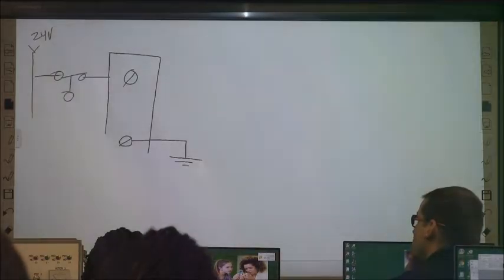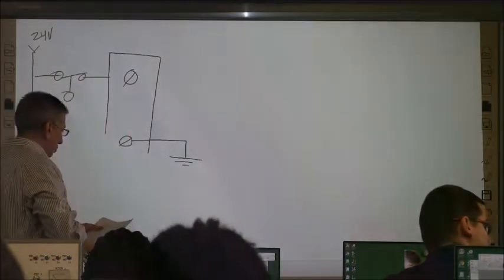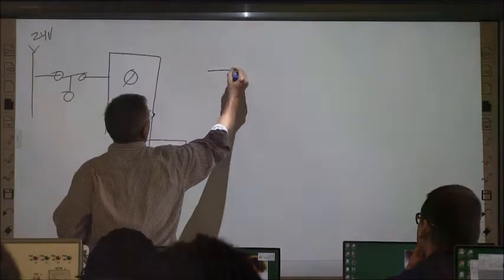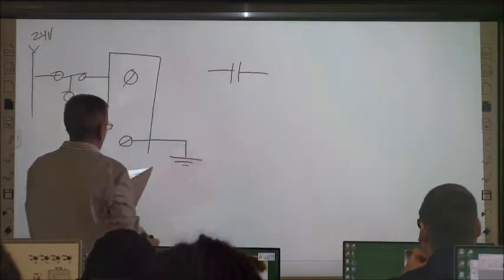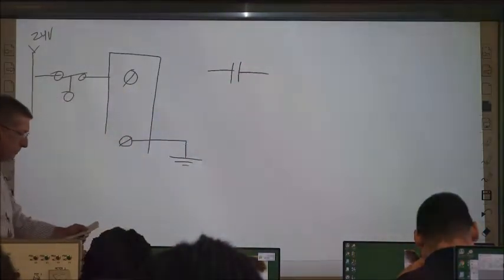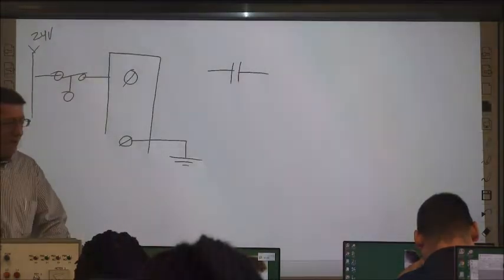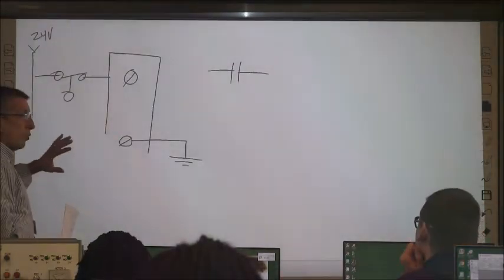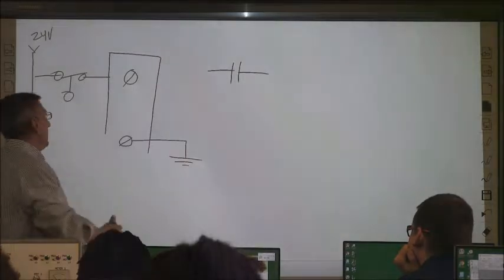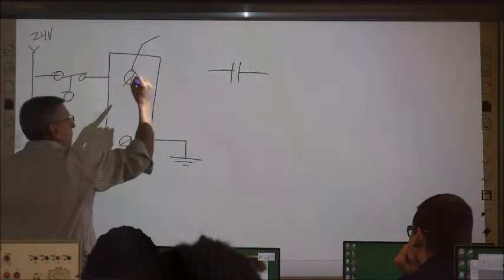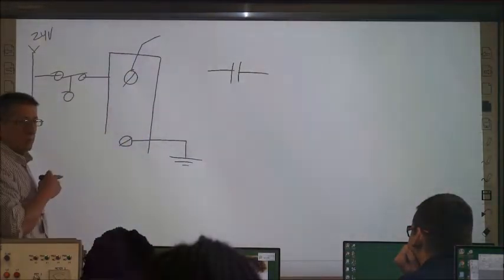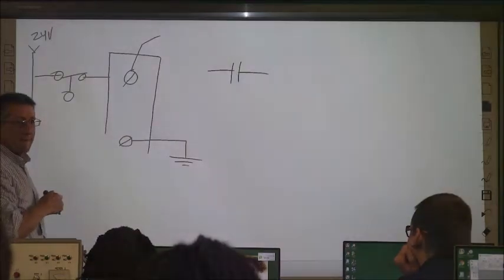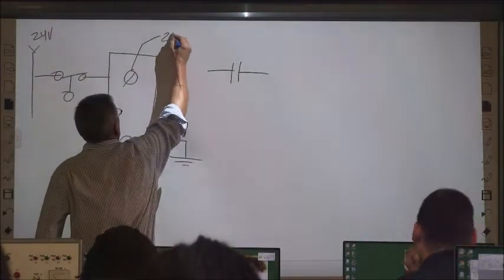The logic for the float switch uses an XIC instruction, but the instruction does not have logical continuity. So right now, while it's in its normal state, what voltage are we going to measure on this input? 24 volts, that's right.